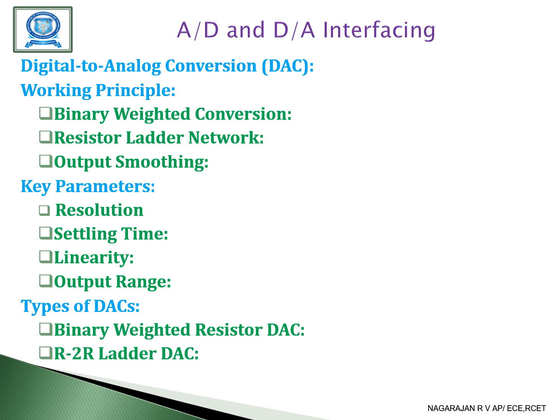A popular and cost-effective DAC design that uses resistors of only two values, one is R and another one is 2R, to create the analog output. The R2R ladder DAC is widely used due to its simplicity and scalability. The next type is a Sigma Delta DAC. Similar to Sigma Delta ADC, these DACs oversample the input and use noise shaping to achieve higher resolution output, commonly used in audio applications.